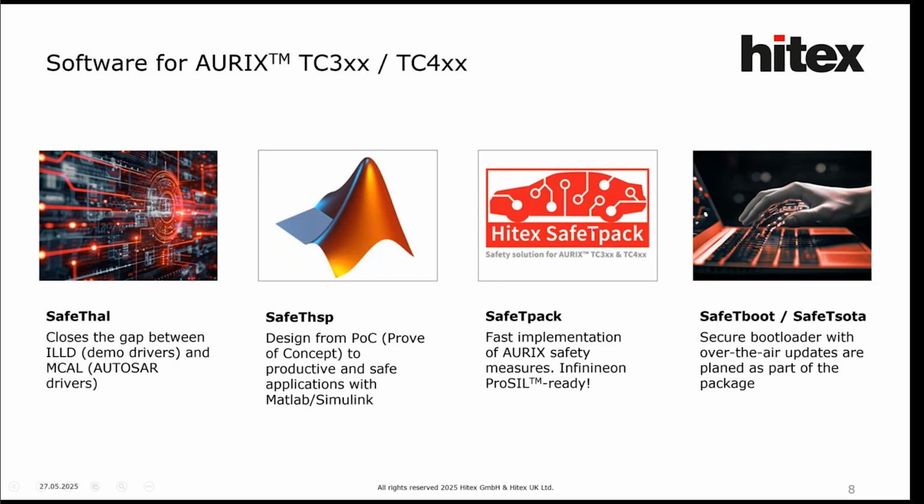The SafeTpack package is part of the SafeTpal family. With SafeTpack, you create a safe startup of the AURIX and implement the necessary ESMs from the AURIX safety manual. The TLF35584 and A5, so the watchdog, is also supported. A secure bootloader and a SOTA package will round off the software package and are planned to complete the package in the future.